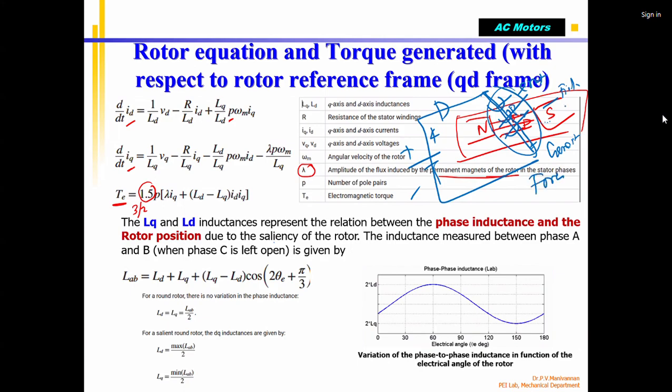Since the stator or field, the permanent magnet, is in the body, the coil is not moving. The wire which is attached in the rotor or armature is allowed to rotate. So the force is able to make the rotor rotate, and the actual force is generated by the interaction between the magnetic field from the current flowing in the coil, the armature or rotor coil, and the stator magnetic field. So this is how it works.